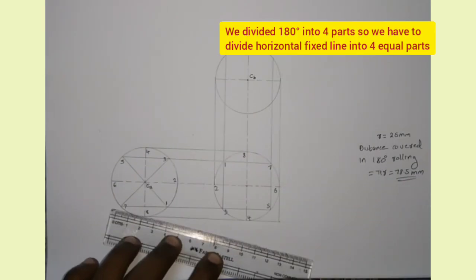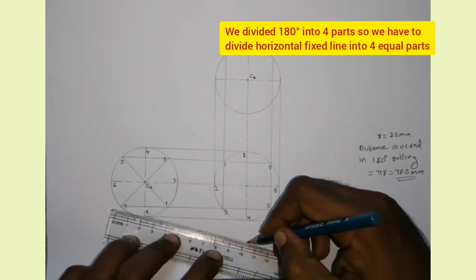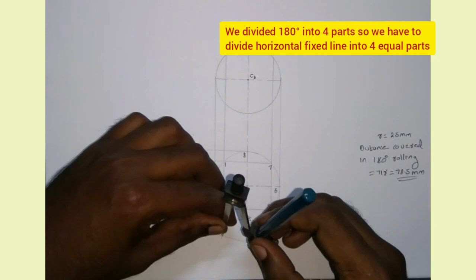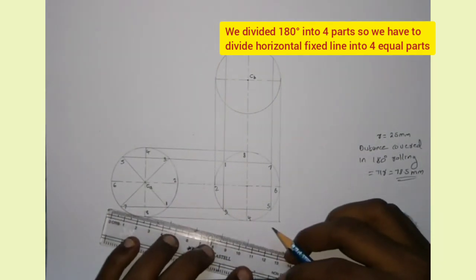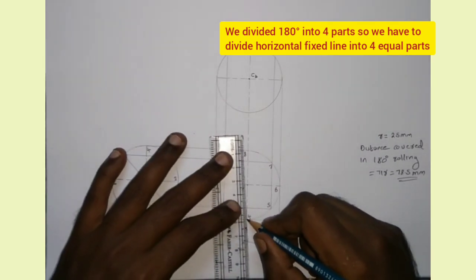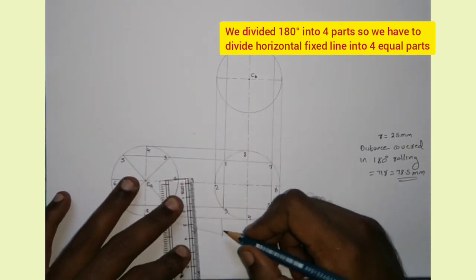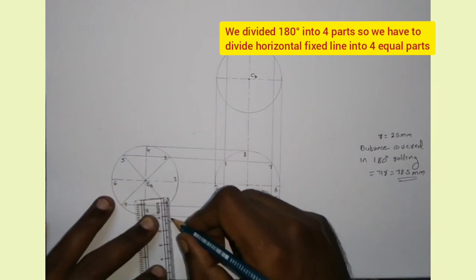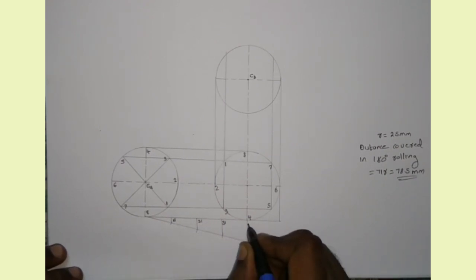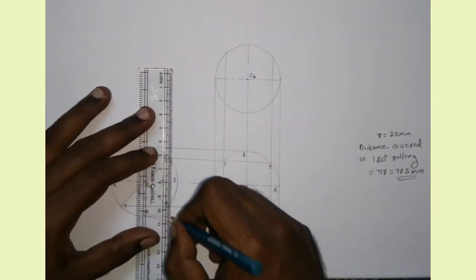Okay, we divided 180 degrees of the rolling circle into 4 equal parts. So we have to divide the fixed line, that is the horizontal floor, also into 4 equal parts. So I am going to divide the fixed line, that is from point 8 to 4, into 4 equal parts. Okay, I am marking points as 1 dash, 2 dash, 3 dash, and 4 is already there. So now I am drawing vertical lines from 1 dash, 2 dash, and 3 dash.